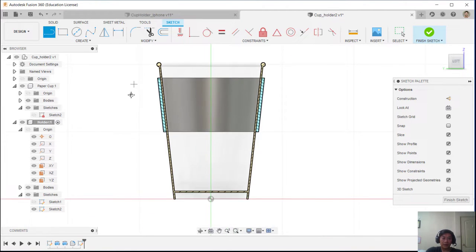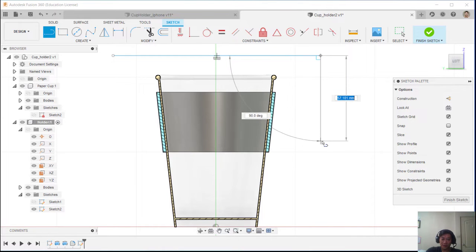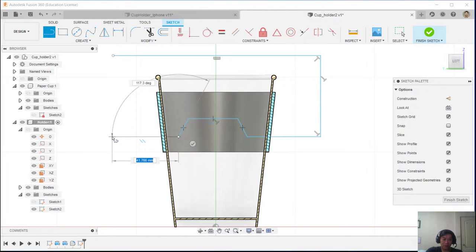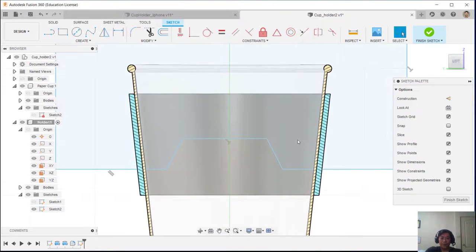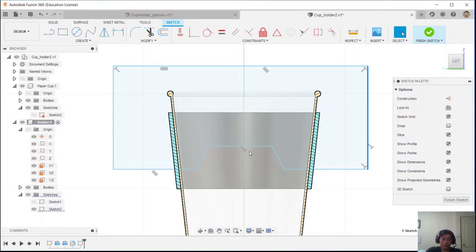and then we can clearly see what's going on over there. Okay, and I'll create a line or a sketch similar to this. Because this is a sketch, I don't need to bother about the shape or the dimension, so I just freely create a sketch. Right now after this, my step is I want to align this sketch to the center. I will use this line as a reference, so I need the construction line.